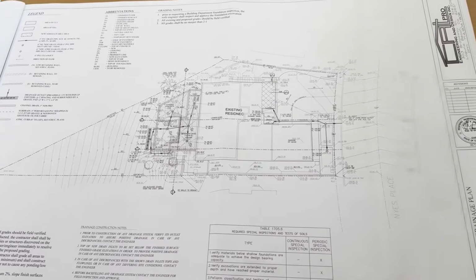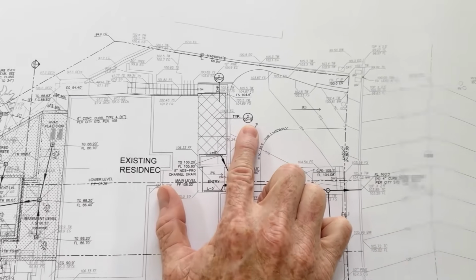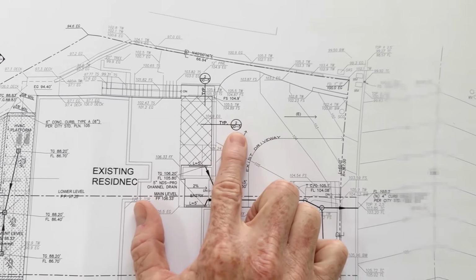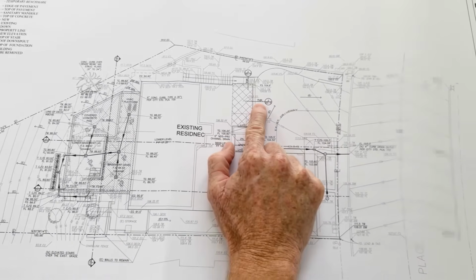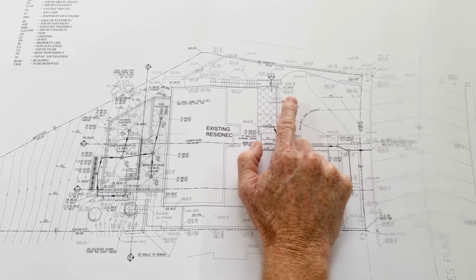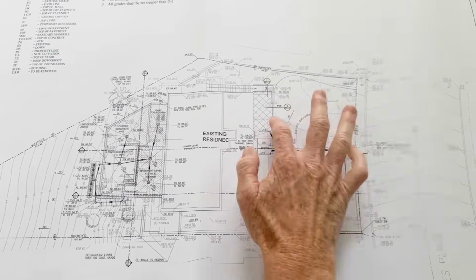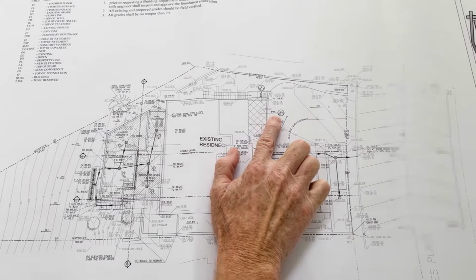What we want to pay attention to is in a situation like this where you've got a subsection or a detailed note where it says, for example, 2 on GD5 in this case, and then there's a TYP next to it, okay? TYP means typical. So anytime you have a condition like this, this would be the note that you would want to follow. So very similarly, GD5.